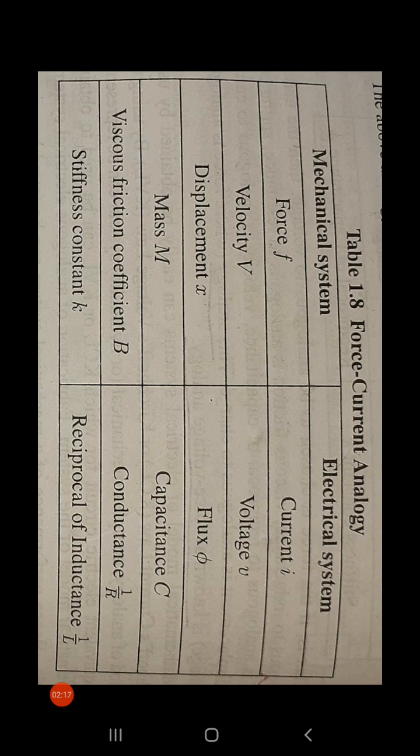And the last one is, if we have a stiffness constant, that is, spring constant in a mechanical system, then this spring constant can be treated as the reciprocal of inductance in an electrical system. So this table represents how we will convert any mechanical element into an electrical element according to the force current analogy.